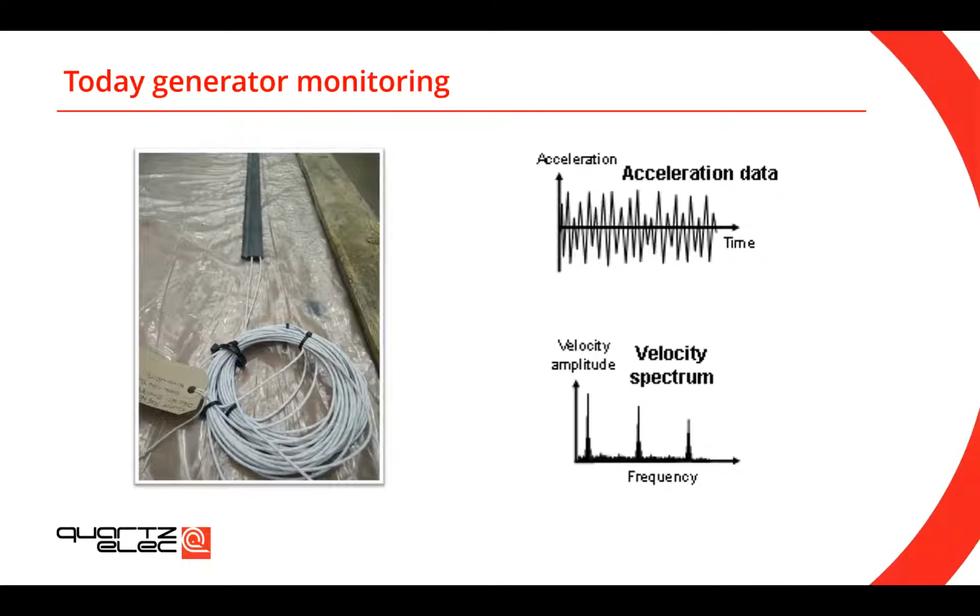Well, because today, our generators are usually monitored using RTDs or thermocouples to measure the temperature of the stator winding, or I presume many of you will have measured vibration of the shaft, and yet there are many more things you can monitor that can save your generator and probably have a lot more diagnostic value than those two I mentioned.